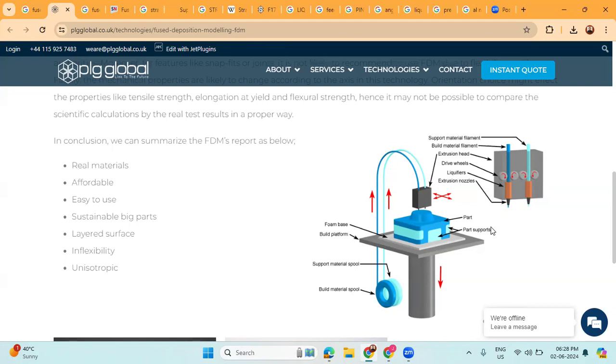Moreover, the support mechanism in wire additive manufacturing is an essential consideration as it directly impacts the fabrication of intricate structures. Support mechanisms can include water-soluble supports which dissolve after the printing process, acid bath supports, or multi-axis kinematics that eliminate the need for additional support altogether. Each support method has distinct advantages and limitations, influencing the manufacturability of complex, overhanging, or intricate designs.